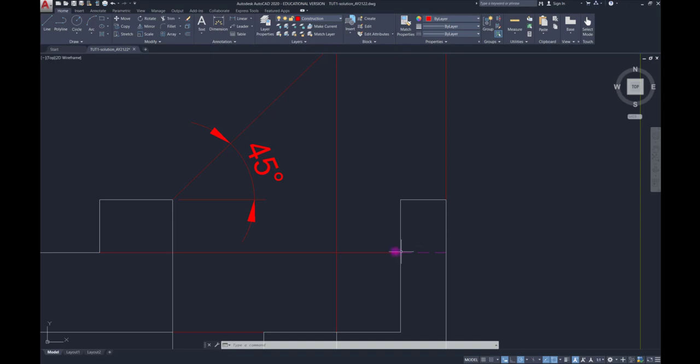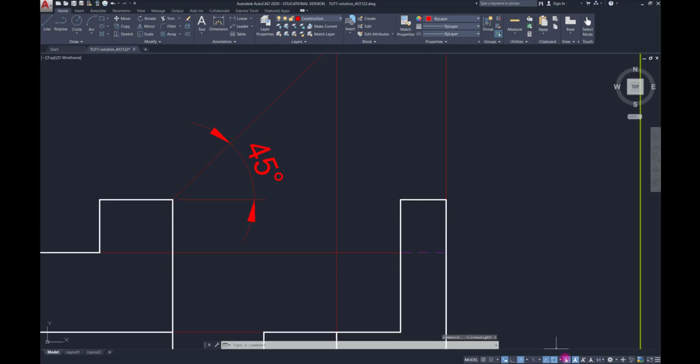For example, the outline is the thick continuous line, whereas the hidden line is a thin short dashes line. So in terms of thickness, the thick outline overlaps the thin line. There is no need for you to actually draw hidden lines all over the edges here.